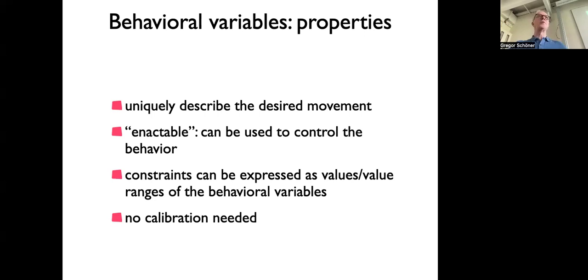It's a little geometry exercise to figure out the relationship between the two wheel speeds and the turning rate of the vehicle. It can be done in a straightforward way, which you do once when you design it. So when I have that time course of desired heading directions, I can derive from that a time course of a variable that can actually be controlled.